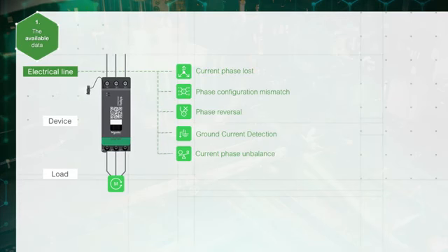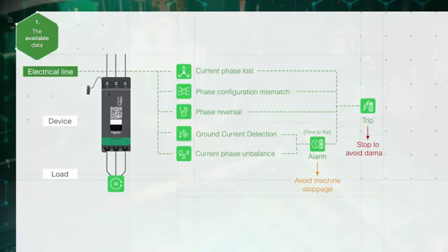At the electrical line level, data about the power supply status is available. This data can be used to send an alarm before the trip and protect the load. Users can set their own threshold using SoMove, EcoStruxure Machine Expert or OMT.